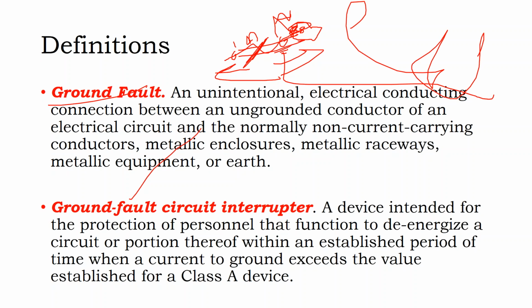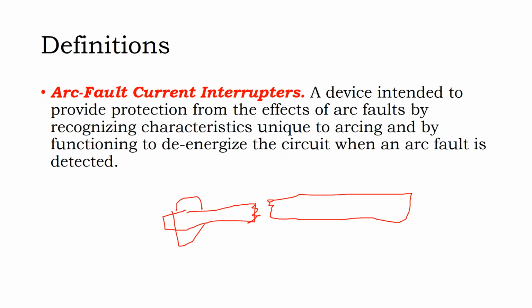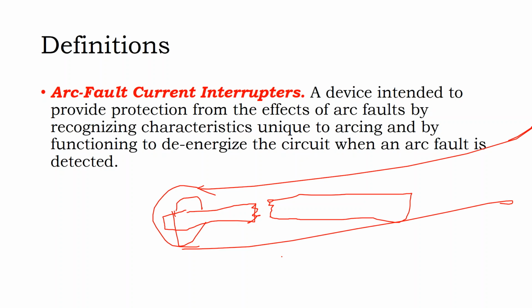You know, that's a ground fault. Arc faults are different. Say you have a cable, and that cable gets pulled apart, so now you have a broken cable, but it's sitting in plastic PVC conduit. Now there's no path to ground, but you have a faulted cable, and you get little sparks that go across that connection.